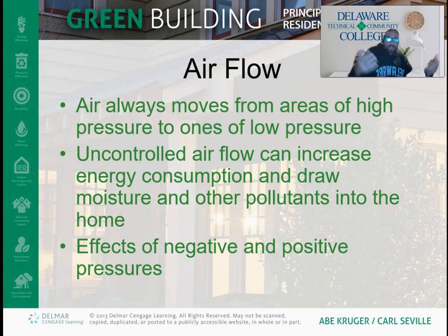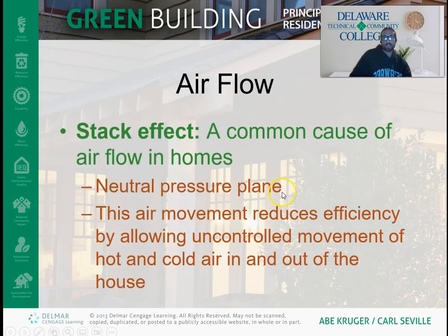So nature's trying to gain equilibrium all the time, where you have a higher temperature here, a lower temperature here, the heat's going to move from higher to lower. Higher pressure here, lower pressure there, it's going to try to move over to the lower pressure. Okay, and so this actually is a really common phenomenon within buildings, but also between the building's interior and exterior.